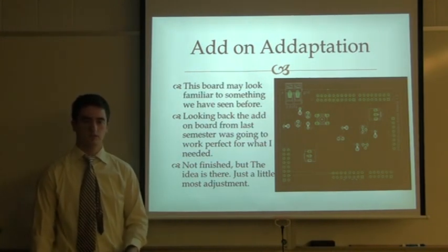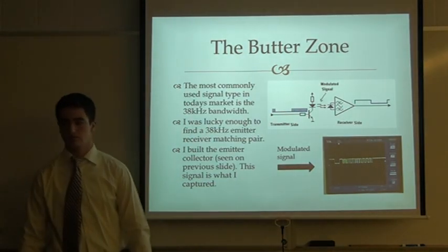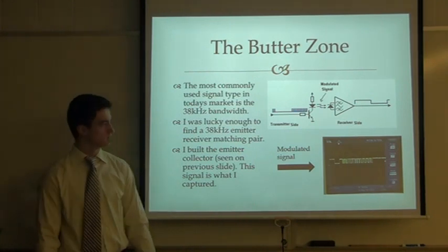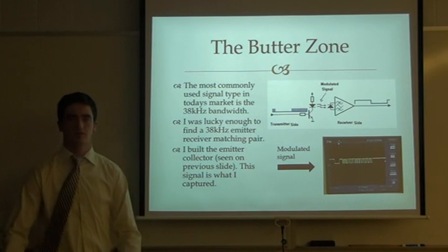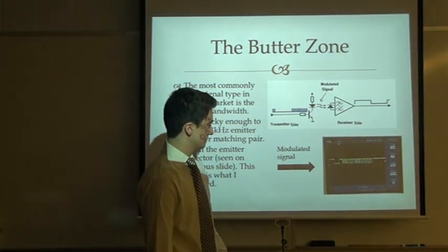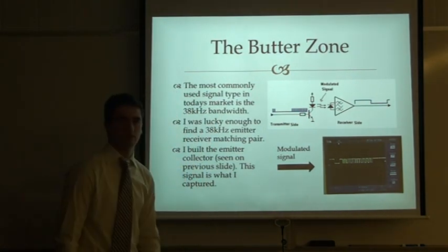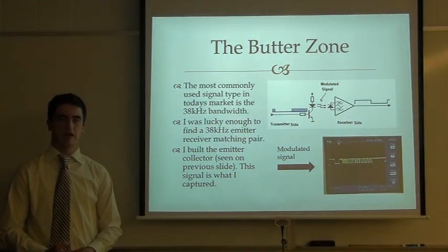If you go back a slide. Yeah. The waveform. So, how much time is being shown in that oscilloscope shot? 10 milliseconds per division. So it's 60 or 70, right? Right. Did you say what that represents? Is that like pushing the up button, down button? That was pushing the power button. Power button, okay. And I didn't mention that. That was the power on.